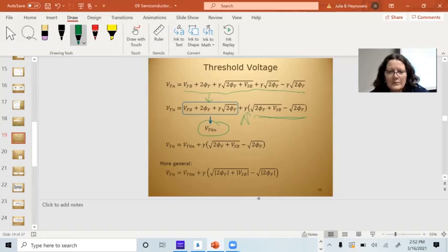So the general term, this is the equation you used in 380 probably. The actual threshold voltage is going to equal VT0N plus gamma times all that. Another thing you're going to need to make sure of if you're a processing engineer down at TSMC is that if someone puts a transistor in a circuit where it has a large VSB, the effect will be small enough that I can still turn the transistors on and off reliably. So that's another piece of the engineering there. This is where you go back to your physics book and start digging through equations and try to figure out how to fix this.